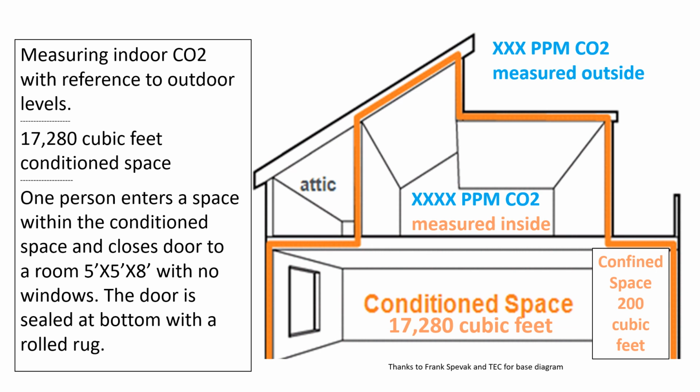Two decades ago, I was the only person measuring carbon dioxide everywhere I went when I was doing energy audits. And to learn about carbon dioxide, you've got to measure everywhere. That's how you learn. So we're going to take a look at this little diagram. We've got 17,280 cubic feet of conditioned space. We're going to measure some outdoor carbon dioxide as a reference. We're going to measure indoor of this huge space. And then we're going to have a confined space, a small little bath and shower room of 200 cubic feet, and we're going to put an adult in there.